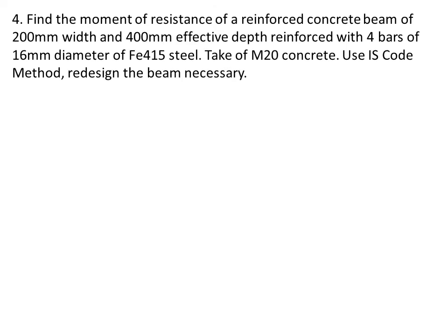Fourth question. Find the moment of resistance of a reinforced concrete beam of 200 mm width and 400 mm effective depth, reinforced with 4 bars of 16 mm diameter of Fe450 steel. Take M20 concrete. Use the IS code method. Redesign the beam accordingly if necessary.